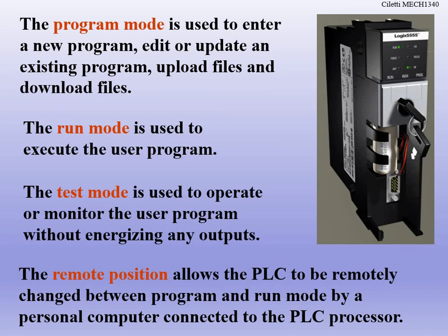So what you're going to do is download your program onto the PLC, and we've probably already done this in class. You're going to download your program to the PLC, and you're going to monitor it at the same time. So you're going to have your program open, and you're going to see what's energized, what's not, and then you're going to use the toggle switches that we programmed to turn on some lights or your stoplight or things like that. We're going to have our 8 inputs and our 8 outputs, and we're going to be working on that part of the trainer for a little bit so that we understand how to control I/O and make I/O turn on and off as need be.